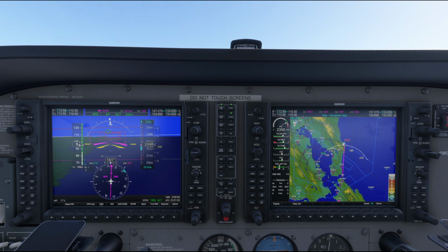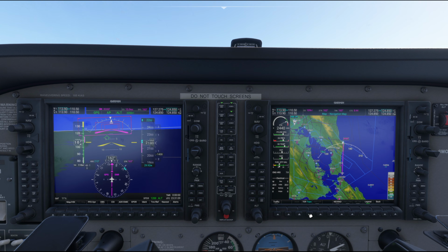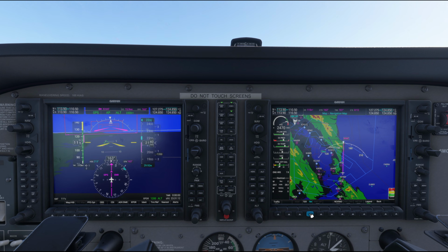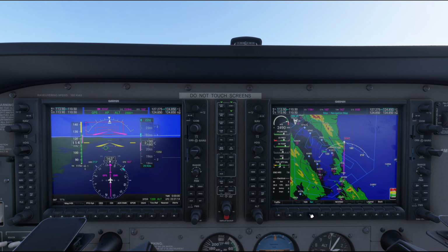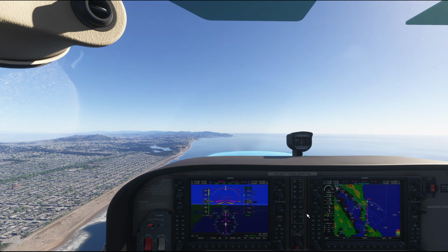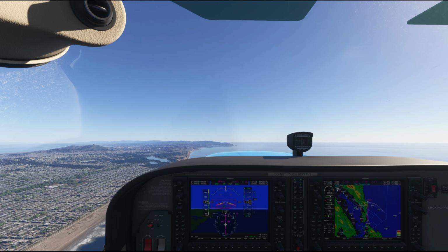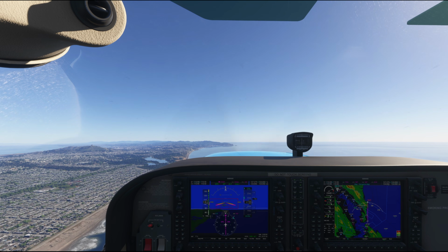There's a problem here, though. This path to Half Moon Bay takes you over a hill just before the airport, so it's not easy to make a smooth descent. It's also generally preferred to stay slightly offshore here for traffic separation and to remain clear of the Bravo. You could do the mental math and plan your descent manually, but there's a much better way, and it works at almost any airport even without a published instrument approach.